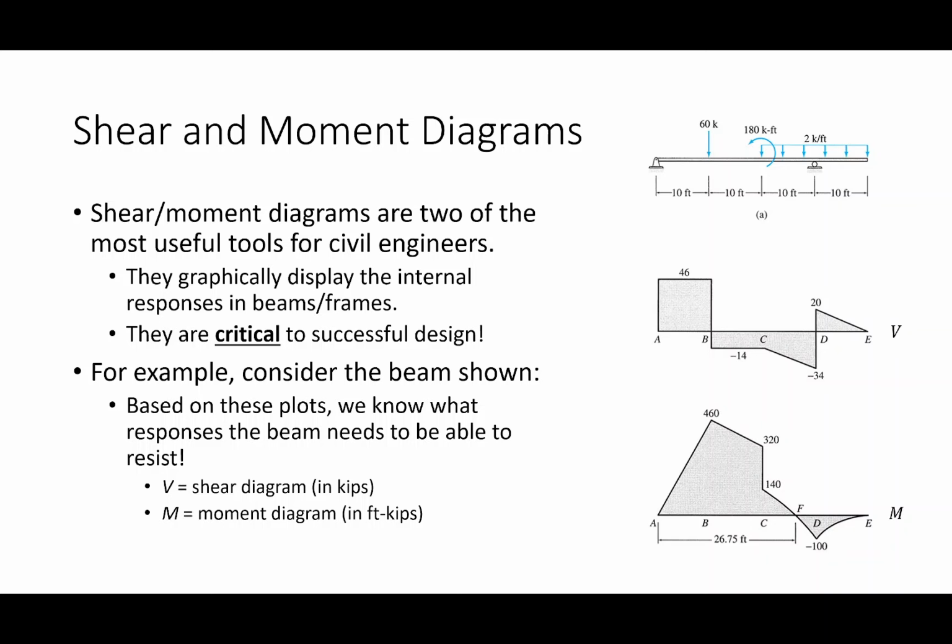And I would say that any system that you design that has an element in it that's being bent, you are going to generate a shear moment diagram. I don't care what system it is. Okay? And so you're going to find that in mechanical and biomedical applications as well. So just to explain what's going on, the moment diagram is a representation of how much the beam is being bent. So the higher up that you get, the more bending there is, the more flexing there is.